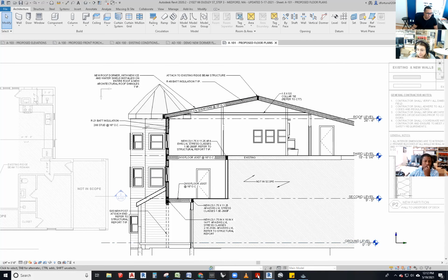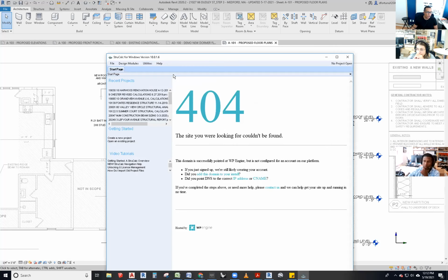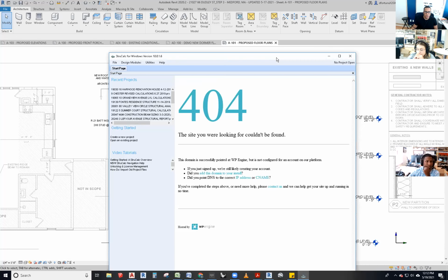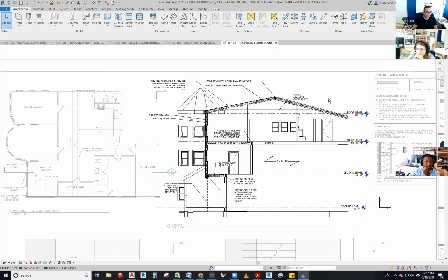So what do we do? Well, I'll open up structural calculation software. And I want you guys to always think about your own processes when you're doing this. How do we do a calculation? First, we should probably start all the way at the roof, know what the loads are all the way at the roof, and move all of our weight down little by little.